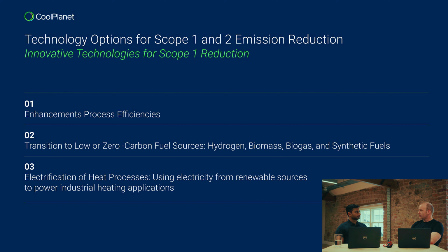Yeah, definitely. You touched on it there, Abhinav, around heat pumps. The nature of a heat pump as an alternative to a combustion source. So just say if you have a traditional boiler, you put in fuel, you have an efficiency. The fuel you put in, you don't get 100% of that as useful energy. You actually only get maybe, depending on the type of the combustion train or the delivery of the heat, 70, 80, 90% of that energy.